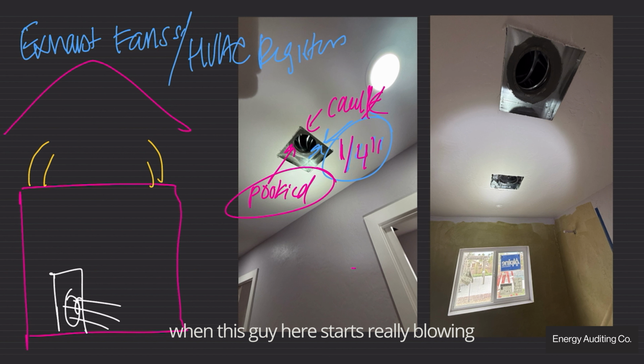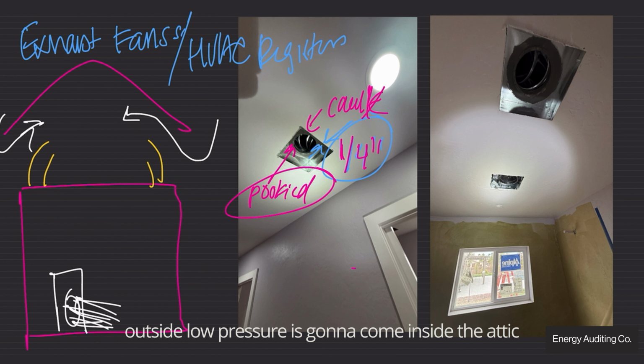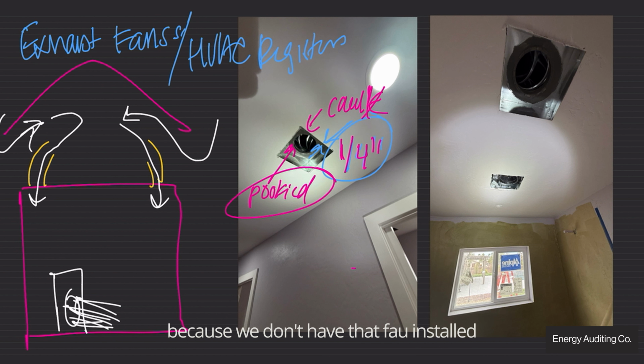When this guy here starts really blowing, what's going to happen is you're going to have low pressure that comes into the attic, right? Because there's going to be lower pressure inside than outside. Low pressure is going to come inside the attic, and then where's it going to go? Right through the ductwork. Your ductwork is basically going to act like two giant openings because we don't have that FAU installed like we had before, right?